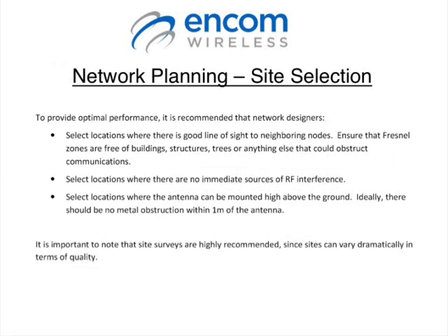When you're choosing a mesh node site, you'd always want to have locations that do have good line of sight to your neighboring nodes. You'd need to ensure that your Fresnel zone is free of buildings, structures, or any obstructions that can affect the communications. You also want to ensure that you're in an area which is not going to be highly susceptible to other forms of interference. For example, if you are in a highly populated area which uses a lot of 2.4 radios, you'd want to definitely stay out of that frequency spectrum.